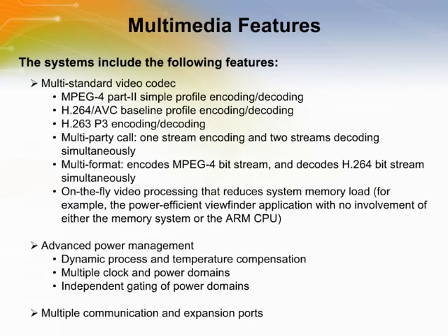The i.MX27 has a built-in, low-power eMMA2 hardware block, which consists of an MPEG-4, H.263 and H.264 encoder and decoder for D1 resolution and image pre-processing and post-processing stages. These features provide superb image and video quality. Devices with the i.MX27 are capable of long video playback time with exceptional video quality. It also provides lower power solutions for any high-performance and demanding multimedia graphics applications.